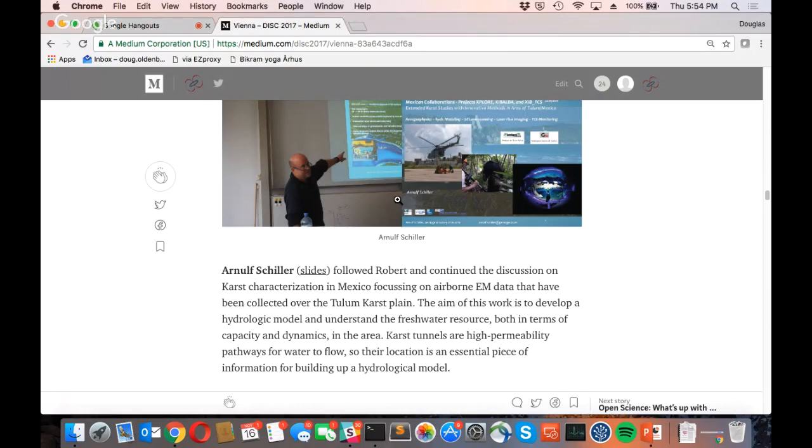Okay, so that's minerals, geothermal. What about pollutants? Yeah, go ahead. Groundwater. So we don't have much to say with regard to mineral exploration, but I guess we can offer to show a few slides on time-lapse resistivity imaging on the infiltration test into the unsaturated zone. What we did is we injected 60 liters per second into the unsaturated zone and had time-lapse imaging running, 1 snapshot per hour, something like that.